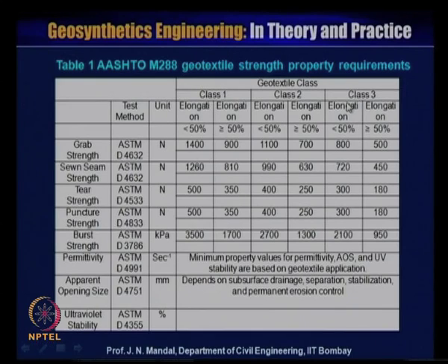This is all geotextile class, and these are the properties we require: grab strength as per ASTM D4632, seam strength as per ASTM D4632, tear strength ASTM D4533, puncture strength ASTM D4833, burst strength ASTM D3786, permittivity ASTM D4491, apparent opening size ASTM D4751, ultraviolet stability ASTM D4355.